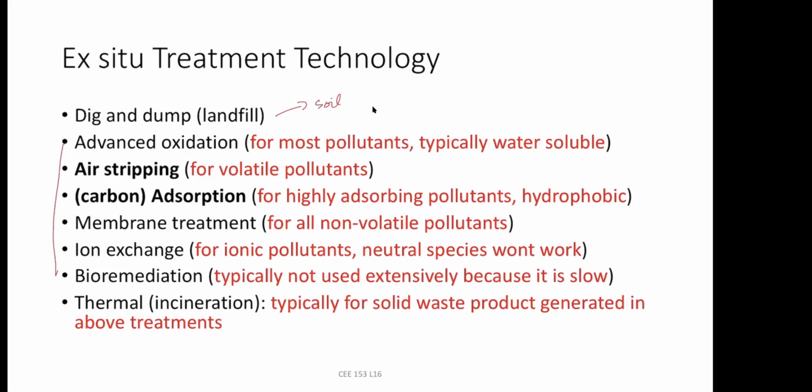Ion exchange, again, it can remove ionic pollutants. So that means if I say, can you remove PFAS, which is non-ionic, then obviously it can't work. So you got to think of all that, but just know when it works, when it doesn't work.